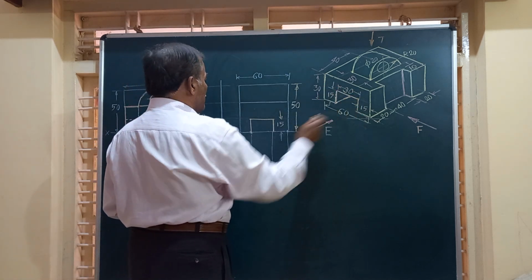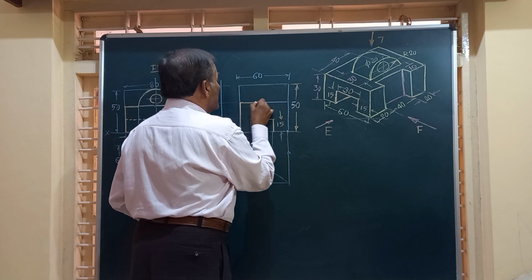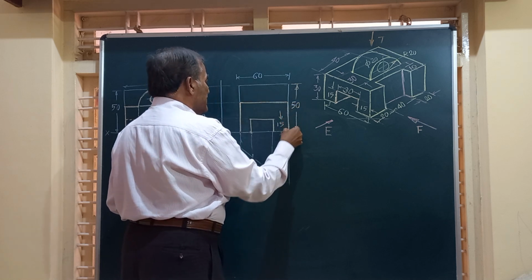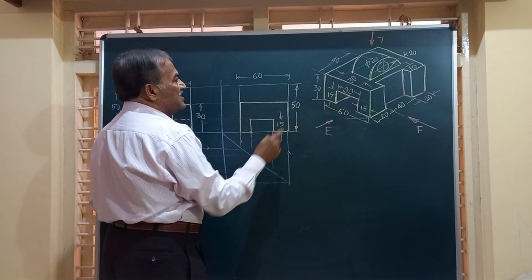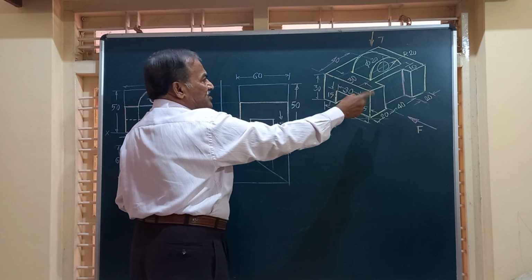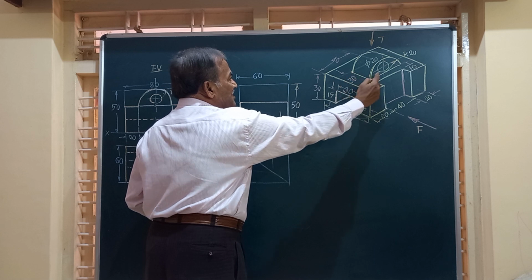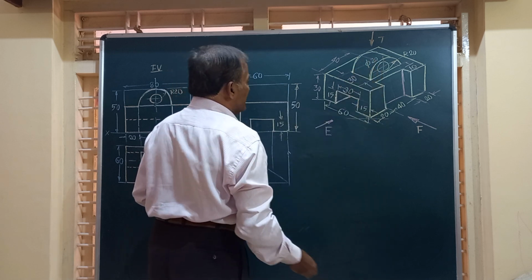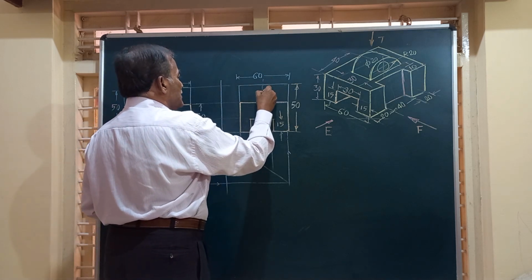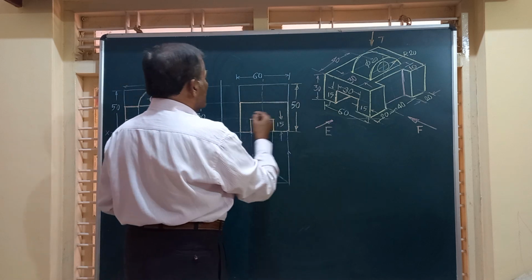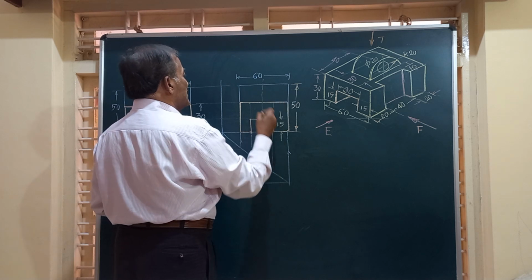In the end view, this C part we have got, let me darken that so that you will be able to visualize how that looks in the end view. I will darken this, I will darken this also. This part is over. Friends, this circular portion, the projection above the flat surface, is seen as a rectangle of this width, and height is equal to 20. Exactly in the center of this, friends, you have got a width of 30.